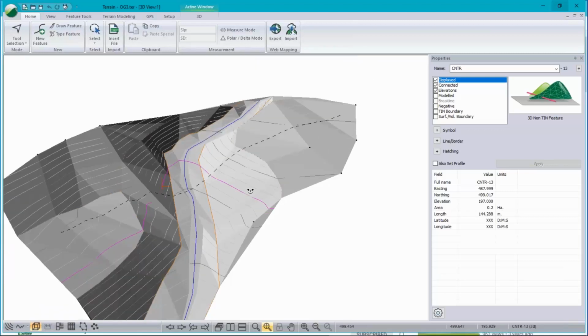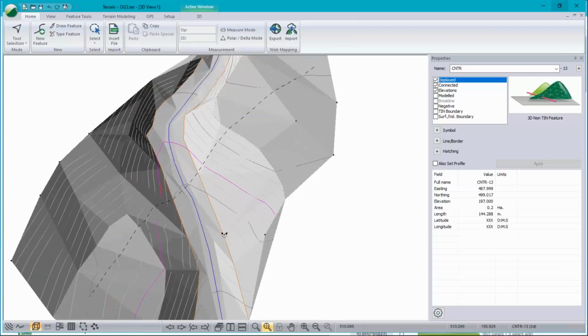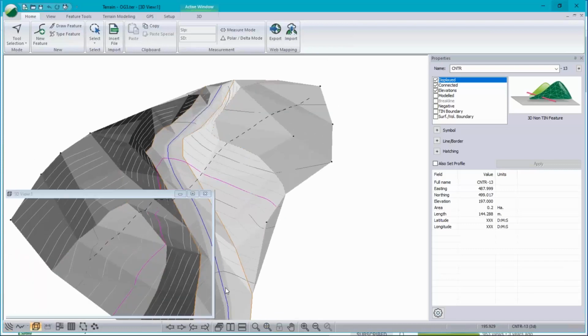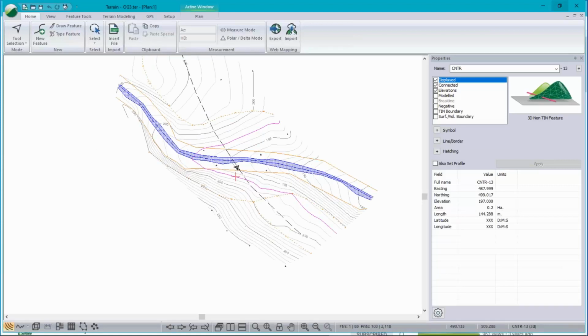Now it's quite common and kind of straightforward to survey along a line and take cross sections. Our survey map module allows you to do that with low-level instruments, compass, clino, and cloth tape or other chain. And of course, you can do that kind of survey with a total station as well. When you've got LiDAR data, you don't have to worry about stuff like that. You just get lots of points. So you might be tempted to just walk along the proposed road and take cross sections. That would require a lot of points to generate the surface as accurately as this has.